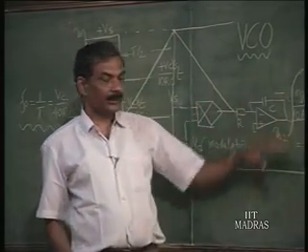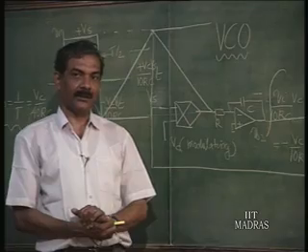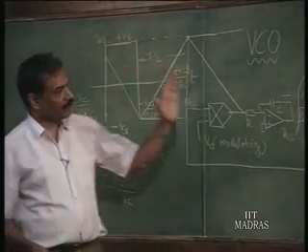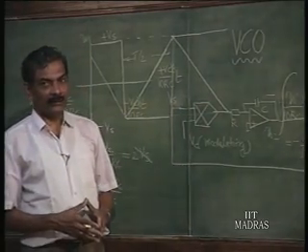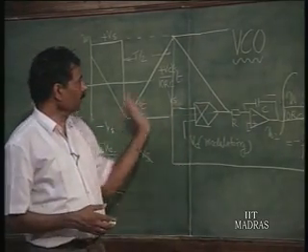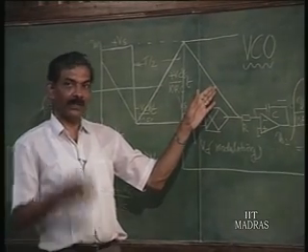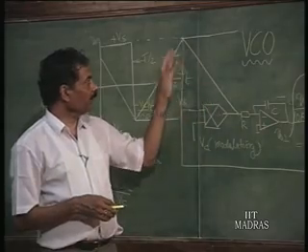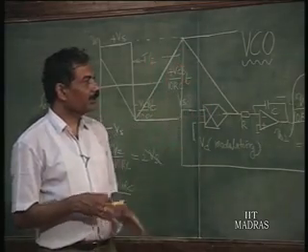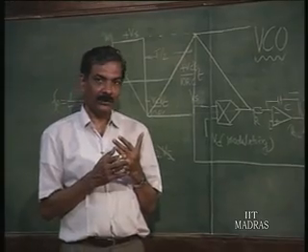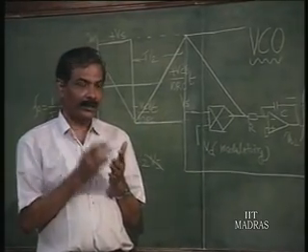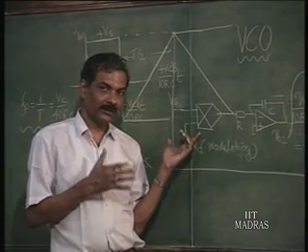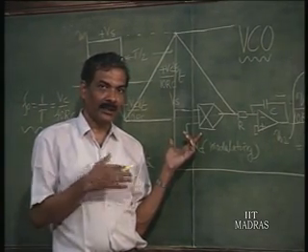this entire circuit is normally called a function generation circuit because it is giving you a square wave and a triangular wave, and also if you put in a function generator, in the sense of a diode function generator, to convert this triangular waveform into a sine wave, that we had done long ago in the first part of our lectures, you get all three important waveforms, sine, square and triangle, with voltage control of frequency. This chip is available as a function generator IC chip.